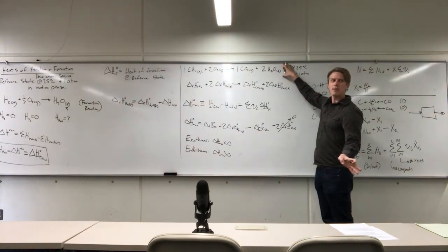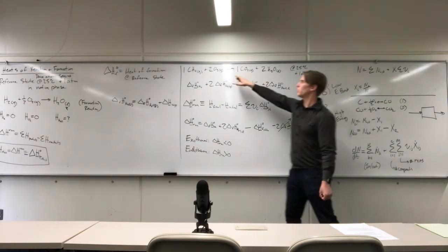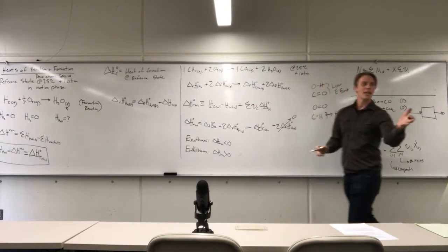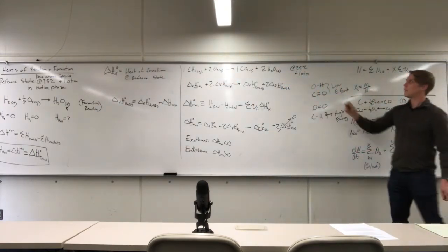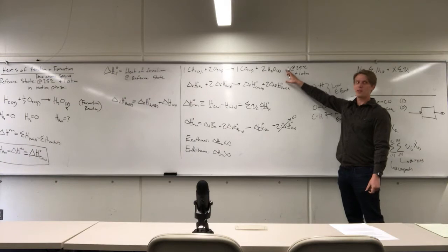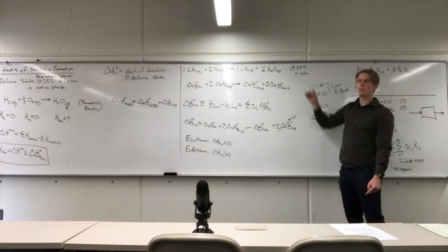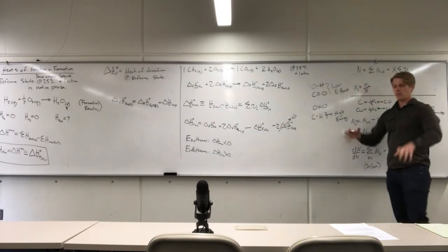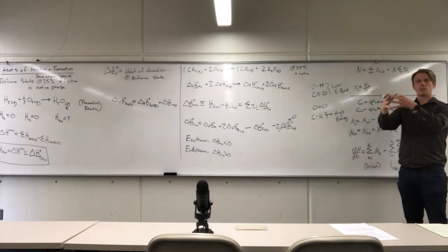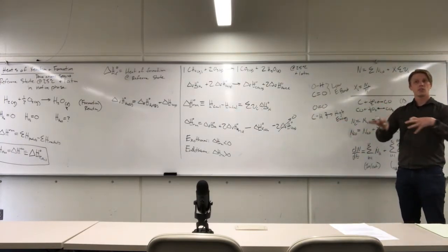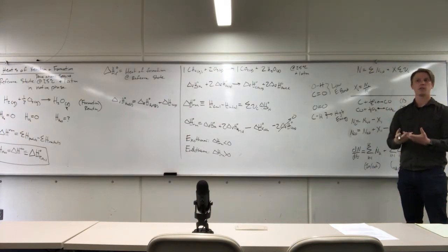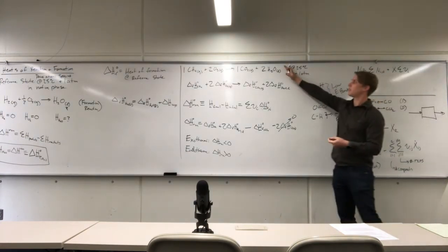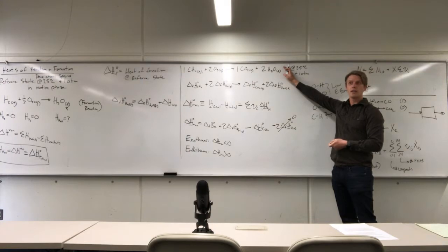It might be actually a little bit higher, because this is being burned in pure oxygen. If you're burning it in air, I think it might be closer to 2,000. If you were to crunch the numbers here, you might be looking at like 4,000 Kelvin or something. It's very, very hot. But if we're burning like a candle, you have a lot of air that's being drawn up that's cooling it down. You're forming soot. That soot has a high heat capacity, so it slows things down a little bit. But in this idealized system right here, this is really, really hot.